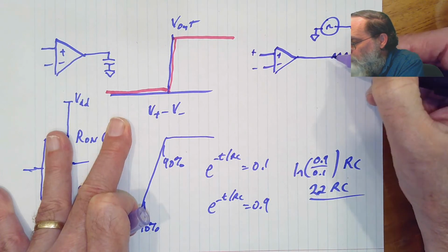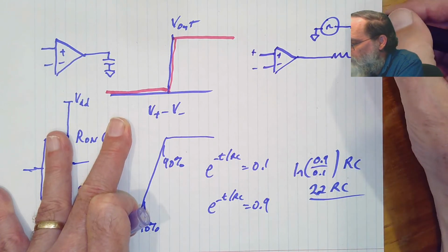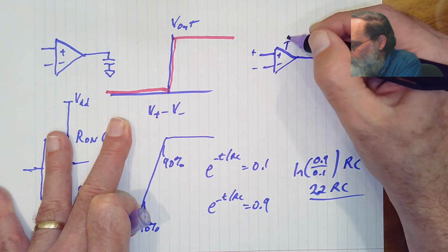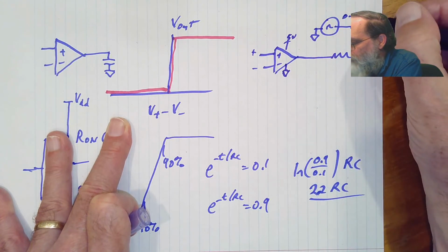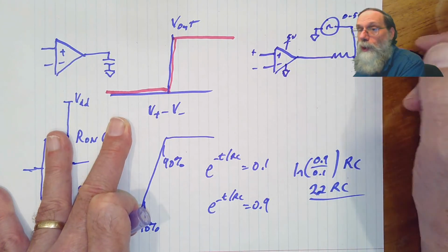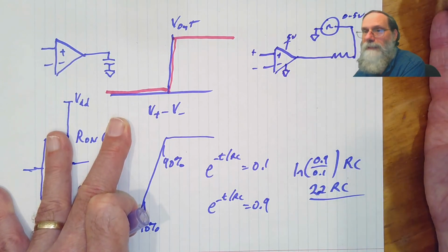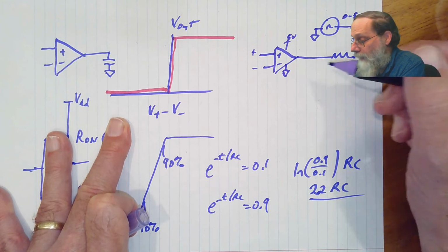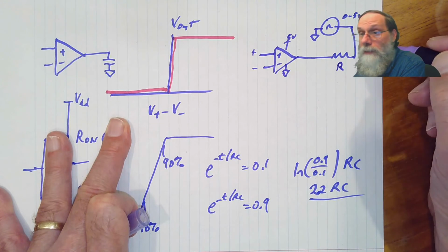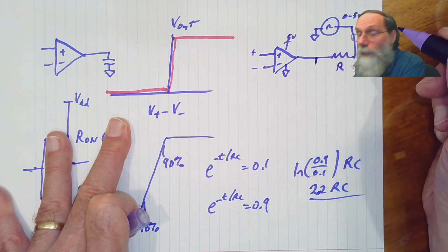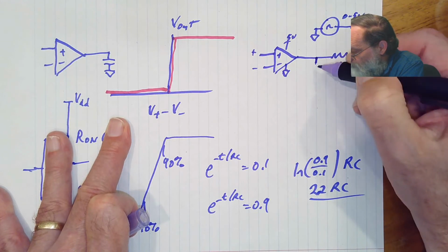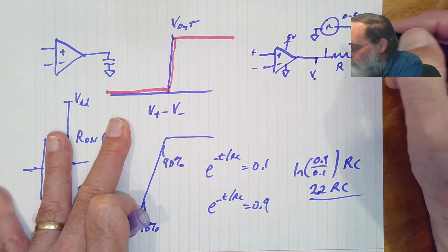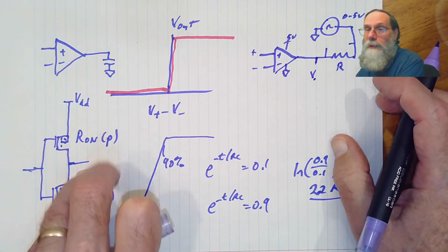So what we need is a drive here that goes from 0 to 5 volts, running with a 5-volt power supply. When this is up at 5 volts and the output is trying to drive 5 volts, there's no current through here, so we get a nice value. But when this is down near 0 volts, it's going to be trying to pull a lot of current. And we can set this resistor to look at what the voltage is here, so that's V out. We can also look at the voltage across this resistor and divide by the resistance to figure out the current.